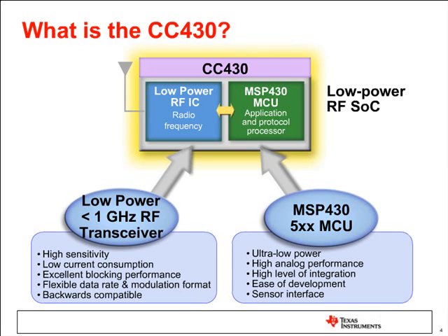So power output, and we'll speak to some of these specifics a little bit later in the presentation, but it's a very flexible radio and is backwards compatible. One of the frequent questions that we get about the CC430 is, does it work with the previous devices, with the CC1101? So if I have a 2-chip solution with an MSP430 and a Chipcon CC1101, will the CC430 still work? And the answer is absolutely yes. It's the same radio, so everything still applies, and that was definitely something that we paid close attention to in the development of the CC430.